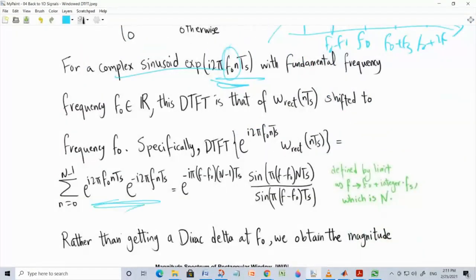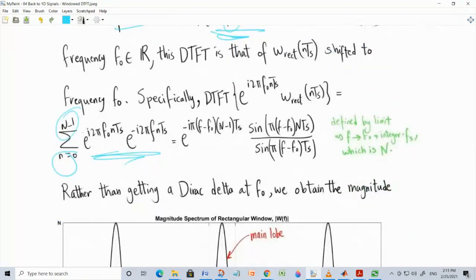So here is the summation. So here is your signal. Now you are picking the DTFT, and now you have a finite number of samples because you are a practical guy. You want to do practical stuff, and in practice you cannot handle an infinite number of samples. You just need to operate on some finite number of samples. Okay, and so what is the windowed DTFT? Well, it's just a geometric series, and so you apply the rule of the geometric series, do some algebra, and this is what you get.